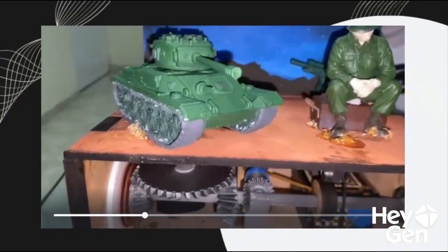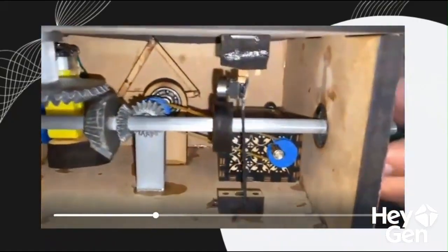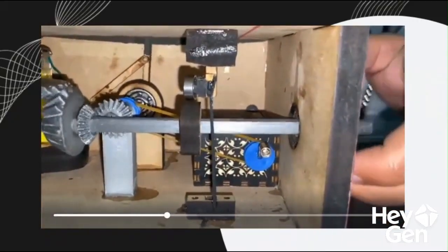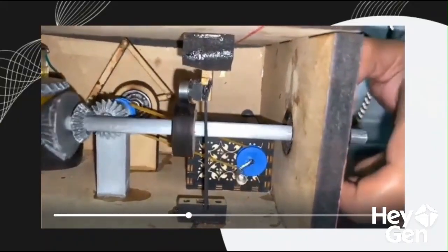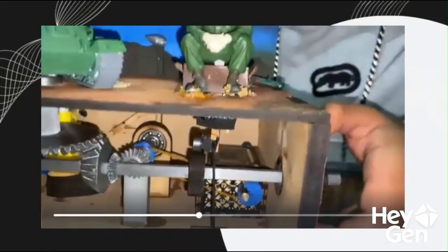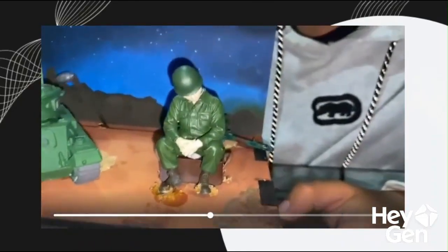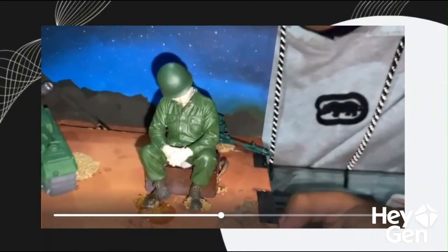Here you can see the final assembly. The main shaft is supported by the bearings in the side covers, ensuring stability and smooth rotation. This shaft transmits the movement from the 4-bar mechanism through a pair of bevel gears. The supports, one laser cut and the other 3D printed, keep the input shaft of this mechanism aligned.